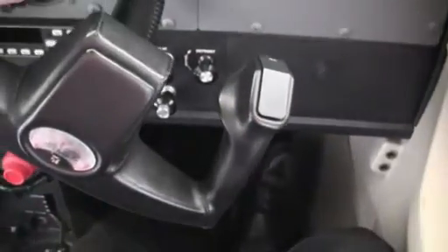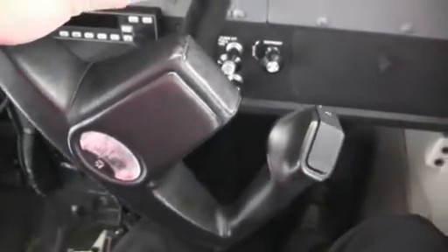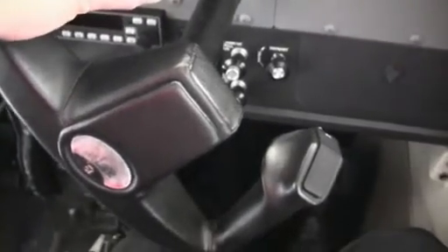With the aileron held into the wind, the takeoff path must be held straight with the rudder. Normally, this will require a lot of downwind rudder pressure, since on the ground the airplane will tend to weathervane into the wind. So rudder pressure must be held to maintain the center of the runway.